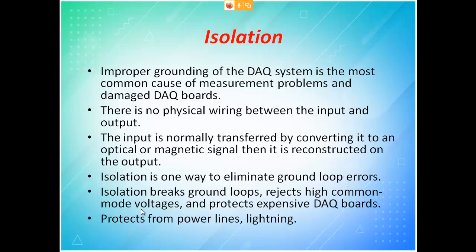So what we do is we do not allow the signal to travel in the electrical medium itself, because there is a chance for noise to get added, because in the environment you have more noise. I think you know why we say this. You might have connected a probe to a CRO. Without connecting to any equipment itself, you will see a sine wave. It will not be a pure sine wave, a distorted sine wave.